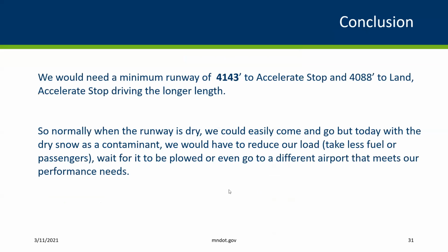So for planning this King Air today, what we would be looking for when you provide us that information, we would say that we really need 4,100 feet, 4,143. So we'd say probably 4,200 feet would be our minimum runway we're looking for. And that would be our driver because it's the longer of our takeoff, accelerate stop, and our landing. And again, normally dry runway, no problem.